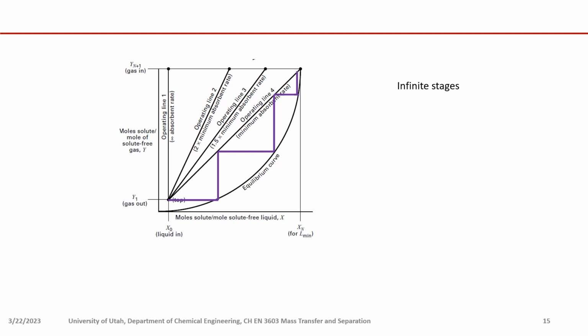And we know that before your liquid absorbent is saturated, it has this capacity to dissolve the solute. That capacity basically drives the mass transfer of the solute from the gas phase into the liquid phase, right? But now you just don't provide enough driving force for doing that.